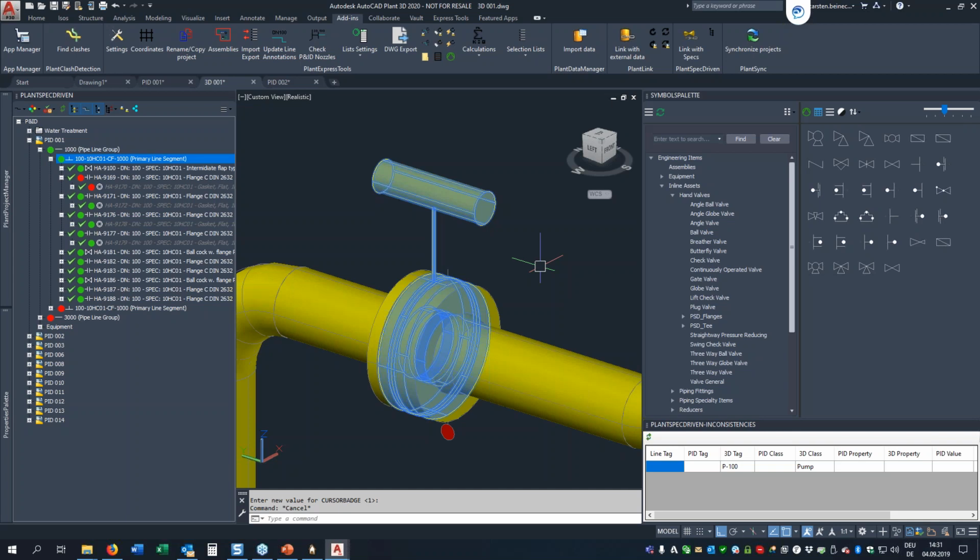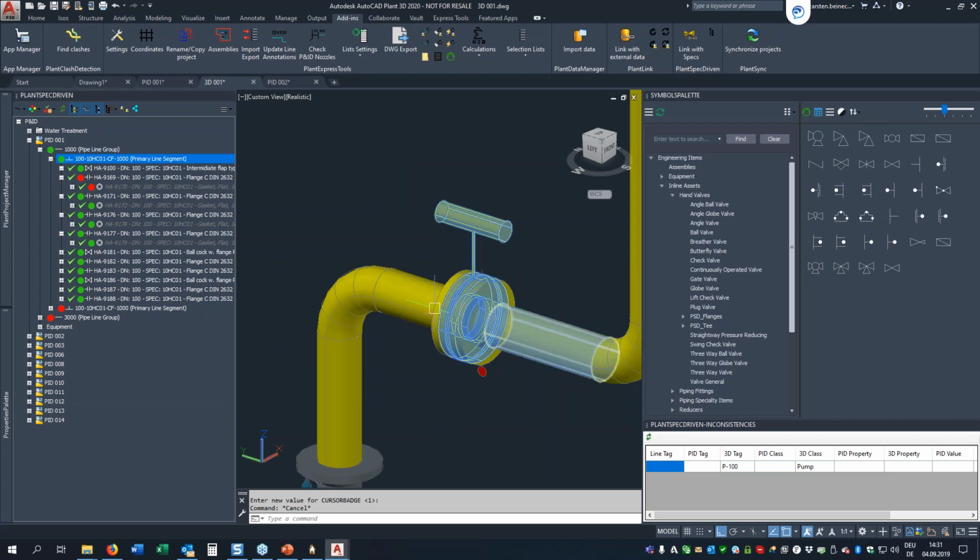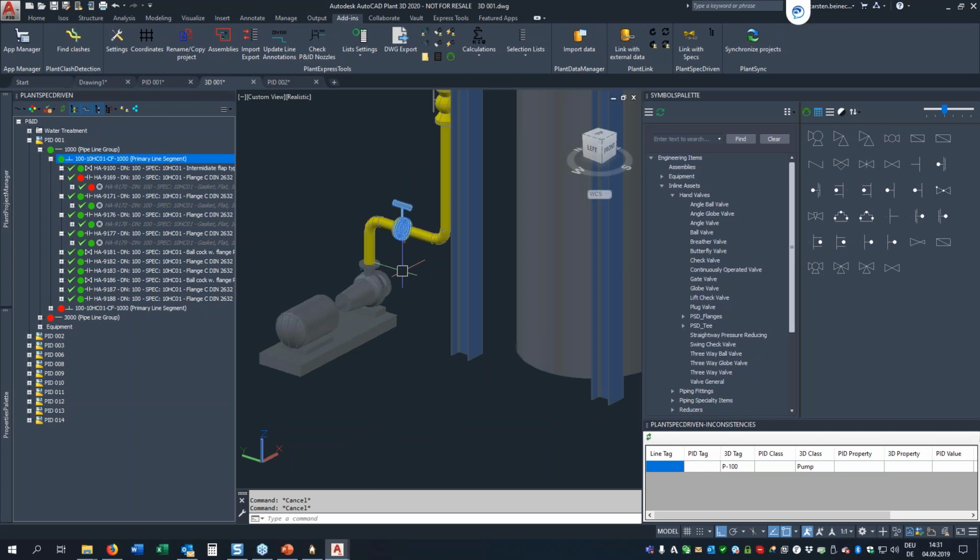Then you could compare, but the graphical slope in 3D cannot be compared because that's geometrical, however you draw it or route the pipe with a slope, and you don't do this in P90. I did not ever see a P90 drawn with a 2% slope or so. Usually it's a slope symbol. But you could use a property and compare the property between P90 and 3D.